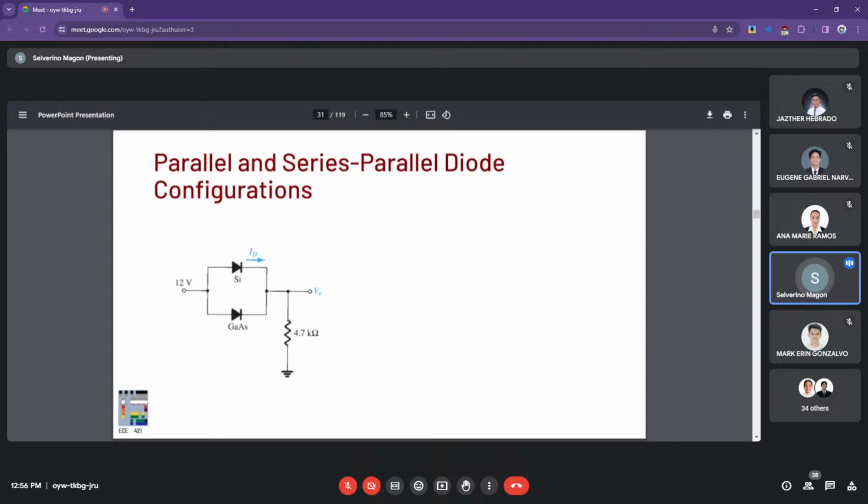Another possible configuration is when you connect two diodes of different voltage drops. All right. So in this case, you have silicon at 0.7 and gallium arsenide at what was that figure previously? Is it 1.2? So what essentially happens here is that once you've turned the silicon diode on, you have a voltage drop of 0.7 across the nodes in between these two nodes, no?